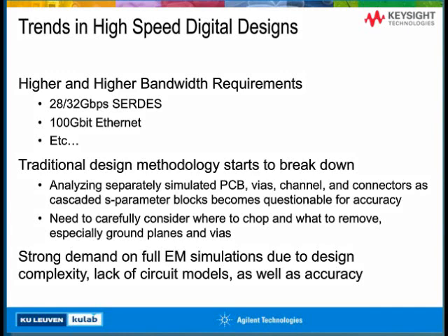What I mean by traditional design methodology is basically analyzing the components of the design, such as PCB, vias, channel, and connectors, as separate components and trying to cascade those as parameter blocks. The accuracy of this approach becomes questionable.